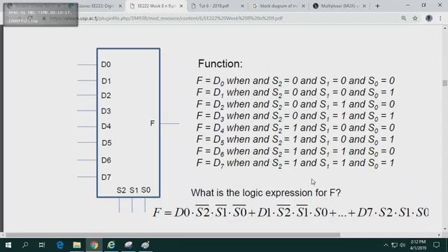Sometimes you will be given a situation where you require 16 data lines. Let's say there are 16 cameras, right? And you have only an 8x1 multiplexer. Or you have many 8x1 multiplexers, but no 16x1 multiplexers. Because remember, the number of data lines has to be accommodated by the multiplexer, right? So what do you do? You can build bigger multiplexers using smaller multiplexers. So just note that down in your exercise book. You can build 4x1 using X. I'm going to leave that as a question mark. You guys find that out on the internet.